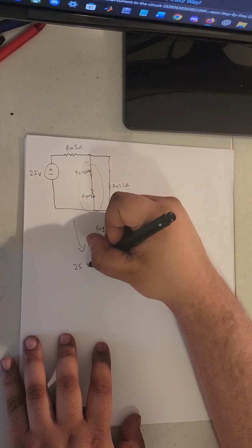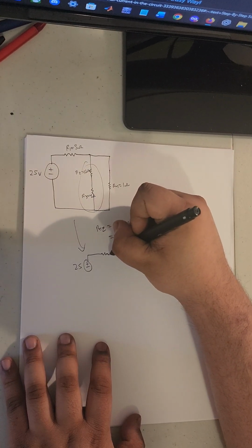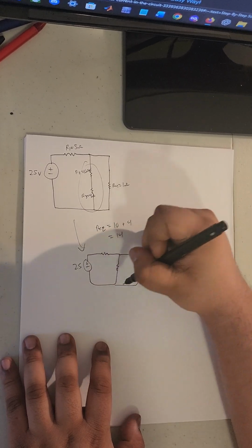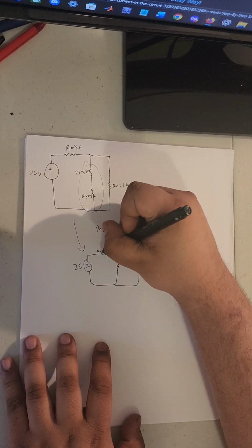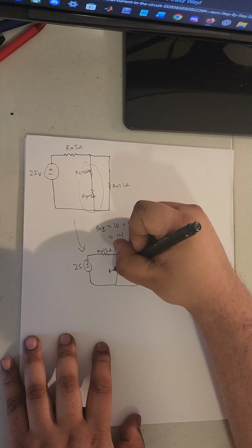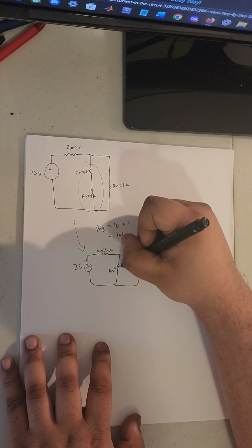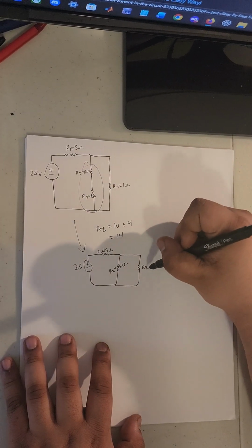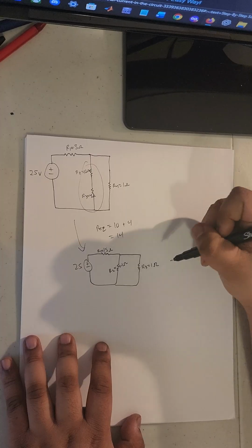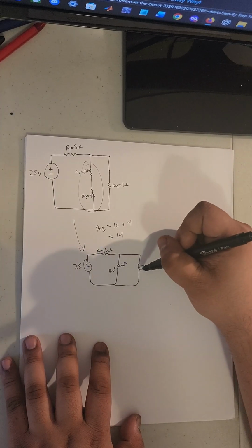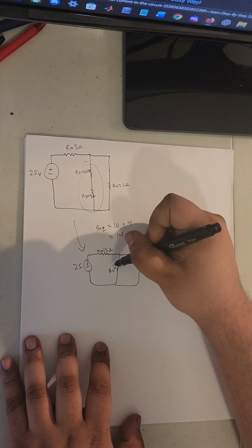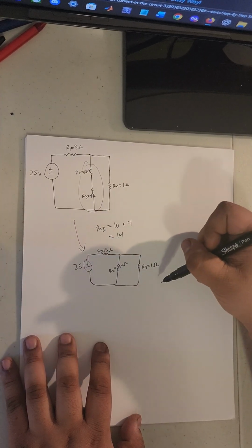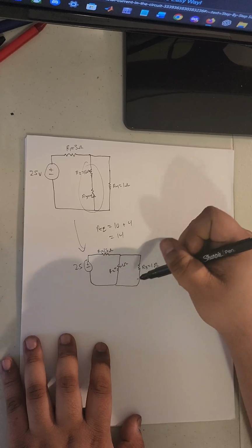Redraw the circuit. You have the 15 ohm here, R1. Now we have, let's say R2 is the 14 ohm equivalent we just found. And here we have 1 ohm, we'll say R3 is 1 ohm. And then we see these two in parallel. Once we do these two in parallel, we can connect it in series with the 15 ohm. We always want to start inward from our voltage source. So these two are in parallel.